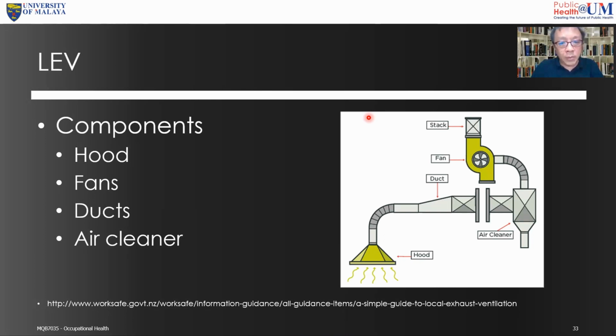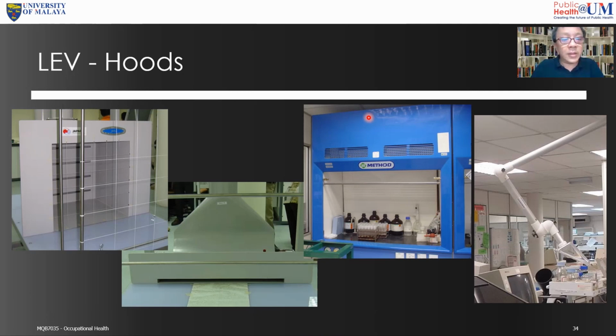So all this must be designed properly by a mechanical engineer, and it must be maintained, and there should be an annual assessment, because under OSHA regulation, you need an annual assessment when you're using local exhaust ventilation, and basically you need a hygiene tech 1 or hygiene tech 2 to actually do it. So the hood design depends on how much carrying capacity or how much suction you want from what you're doing. So it depends on what you're doing, and on the chemical or the hazardous substances you are using.